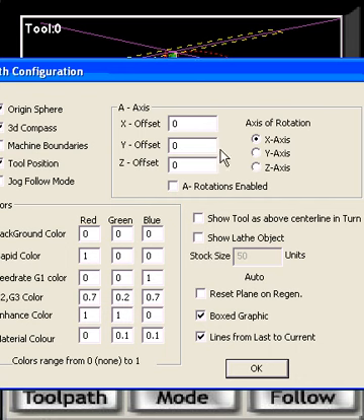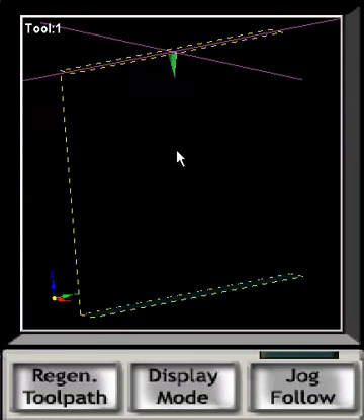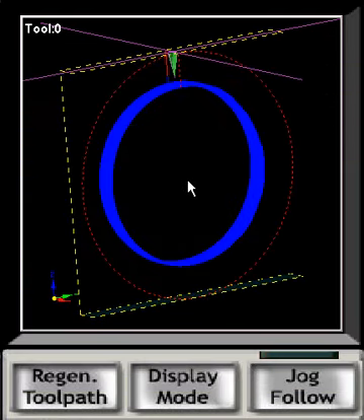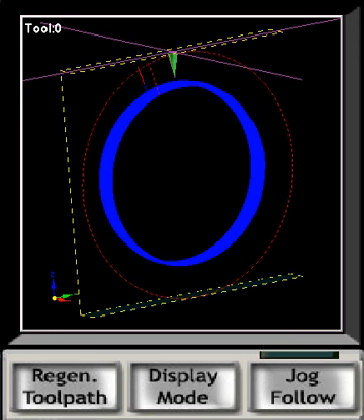So you should enter numbers in here which are proper for your rotational table. That will make sure that the display lines up with what you have selected. Now, a couple things you'll notice about this display. If I start to jog my A-axis, you can see the display itself rotates. This is because you're meant to see on this screen exactly pretty much what you see on your table, the A-axis rotation rotating as the job gets cut.